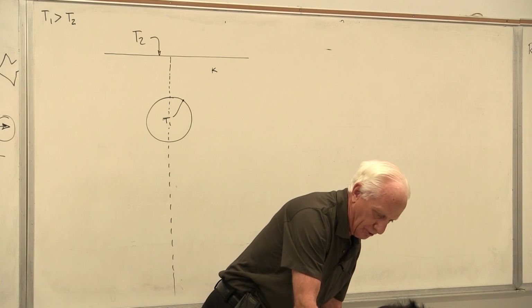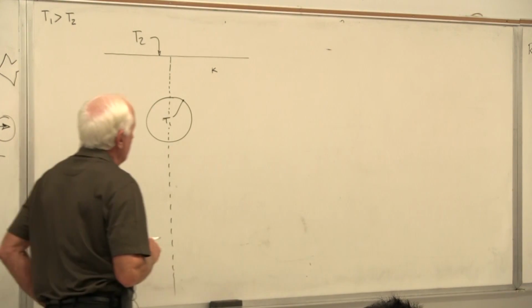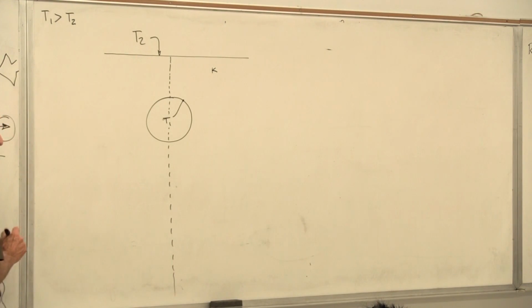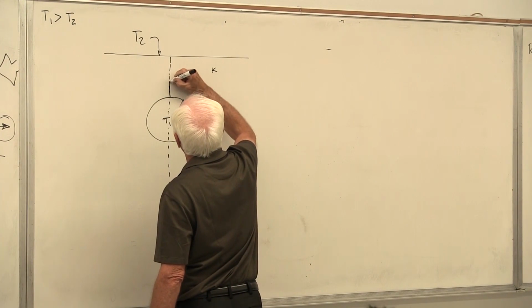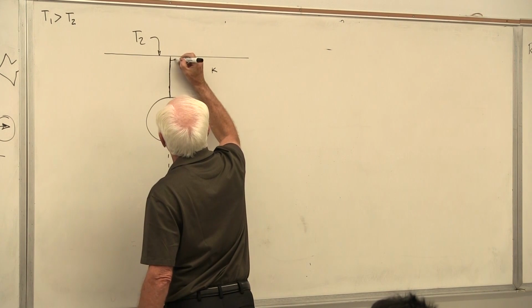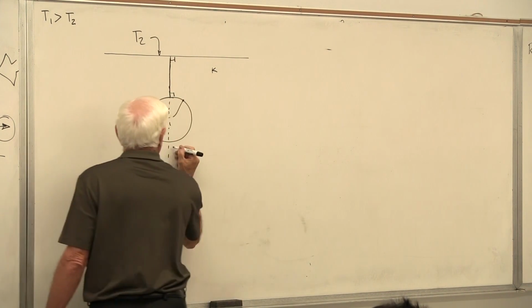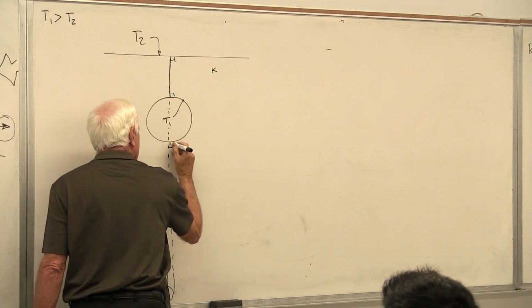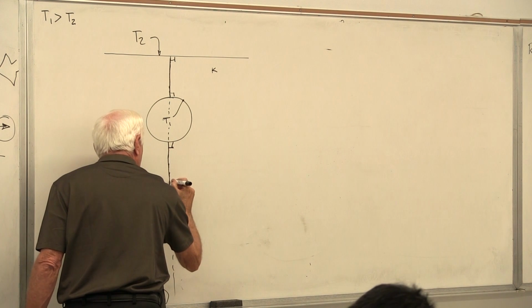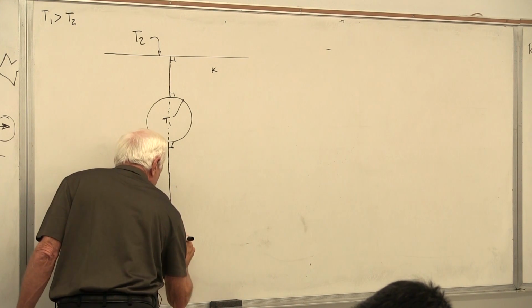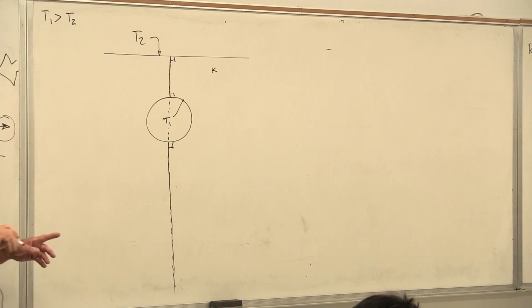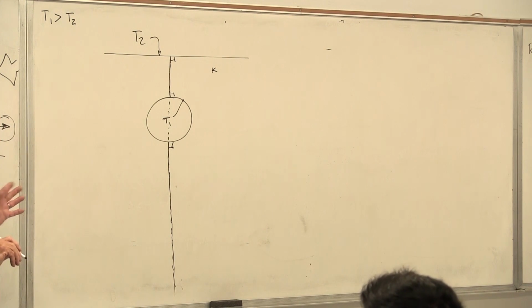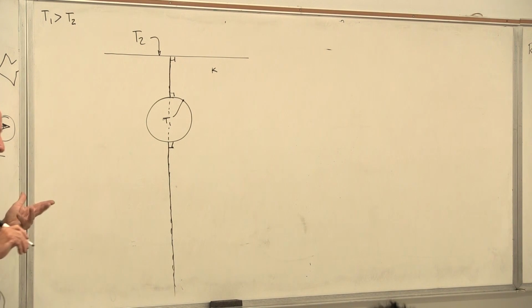That line, rule number two, is automatically an adiabat, a heat flow line. Yeah, that makes sense, of course. Heat leaves here and goes straight out the top of the soil surface there. Right angle, right angle. Here, this is a heat flow line going straight down. Right angle. I'm going to draw the heat flow because I have some intuitive feel for that.